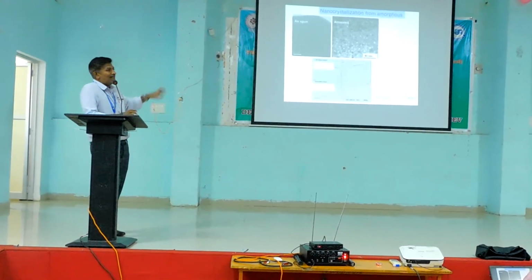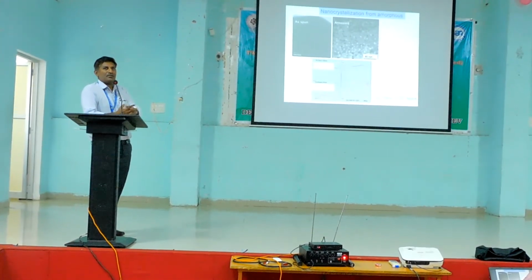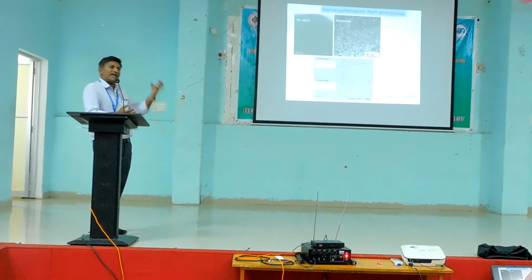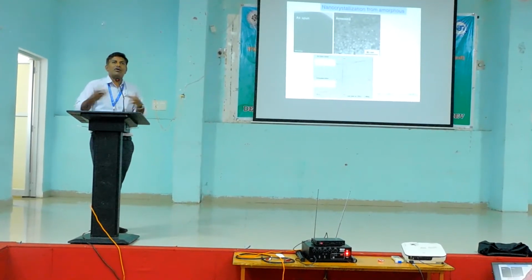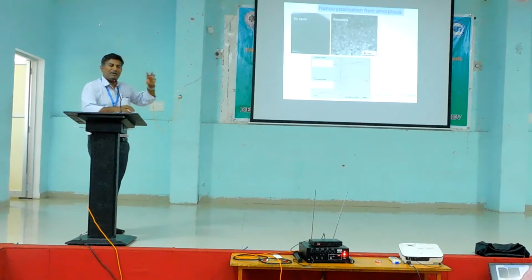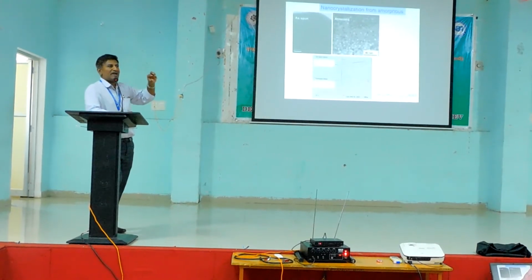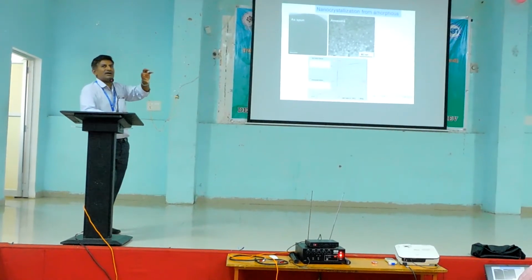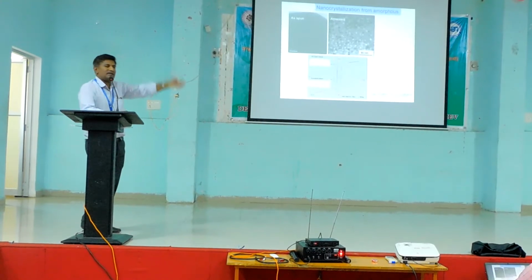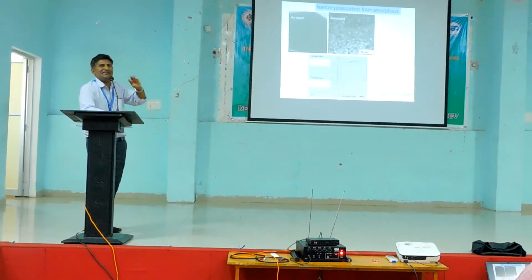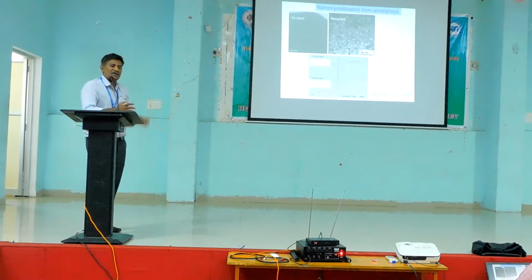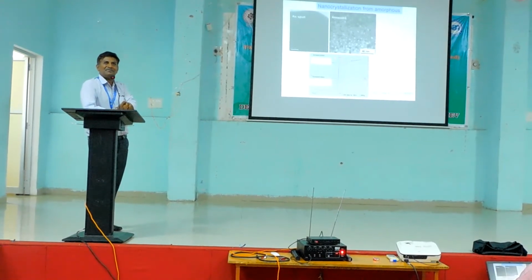Now if you have a nanocrystalline material, again you can say that now there are more grains or grain boundaries. But people have found that the domain is still smaller in your nanocrystalline material. So again the losses will be less. There is one theory, like you must have come across the inverse Hall-Petch relationship.